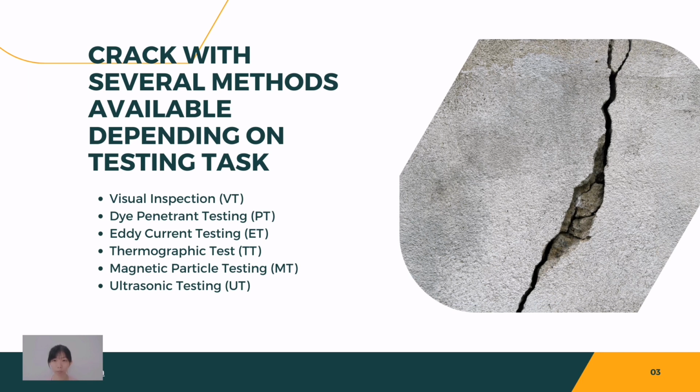During visual inspection procedure, the surface-related quality features like shape deviations, defects, or the surface condition of a component are observed and assessed with the naked eye or with the aid of optical devices, such as magnifying glasses, microscopes, or endoscope. Another test is with eddy current instrument.